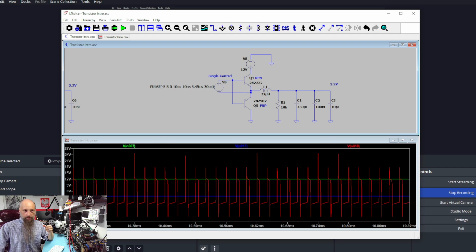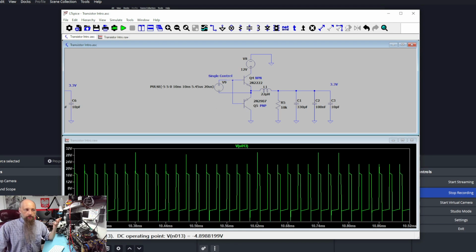This is our reference voltage, which we're measuring against the ground. So we see a lot of spikes, a lot of weird things. But the reason for that is that we're measuring against a stable ground, while our reference voltage should be the negative of this power source V9. That allows us to control only one signal, to control the whole device with just one signal.